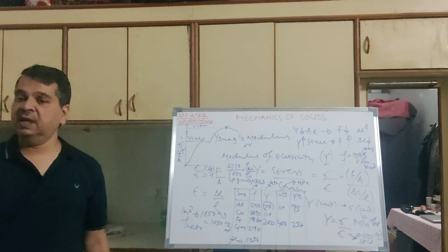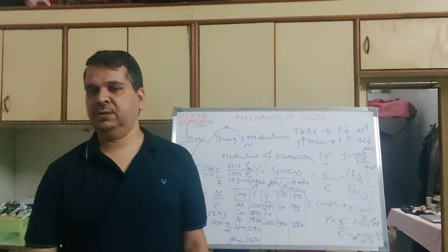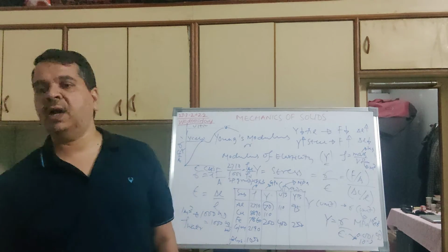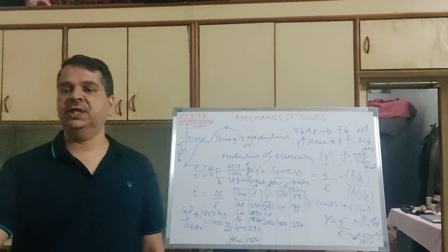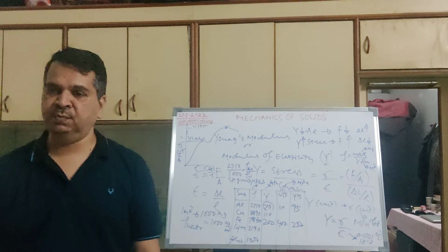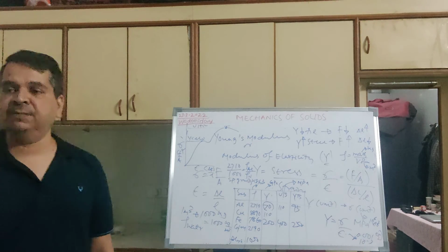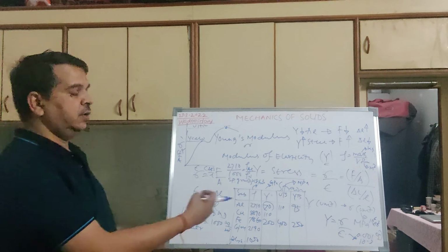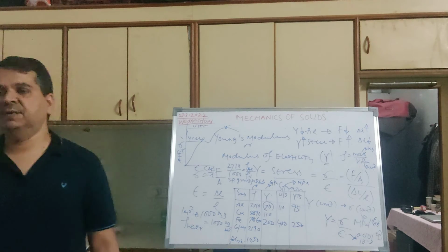Normally they say that we should not remember anything, we can refer to everything, but that is not true. You should remember some values so that you will have a feel of it. At least you should remember aluminium Young's modulus is 70 GPa, steel Young's modulus is 210 GPa. That's all. Then specific gravity: aluminium specific gravity is 2.7, steel specific gravity is 7.8. This you should remember to have a feel as compared to water, how heavy it is. Okay. So similarly, ultimate tensile strength and yield strength. These values you should remember to have a feel.